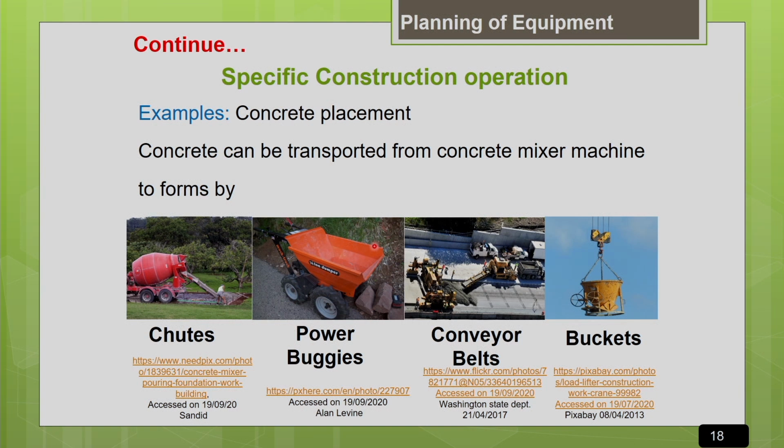Concrete pumping is commonly adopted for placement. Or I can go for a conveyor belt like this, if the rate of placement needed is very high. Or I can go for even a crane with buckets. If the concrete is to be placed at greater heights, then I have to go for a crane with concrete buckets. We can even go for a helicopter with a concrete bucket, depending upon your job site condition.